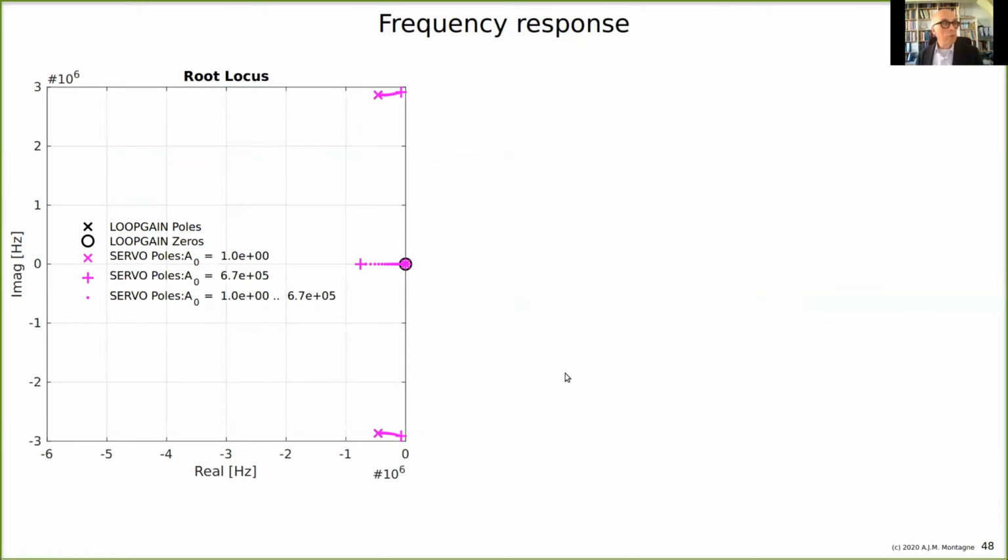And if we then make the root locus for our amplifier, then we see that the poles are moving closely, these complex poles, closely to the imaginary axis. So I'm expecting a lot of ringing and almost unstable behavior. So this is the dominant pole, and these are non-dominant poles. You see here, the frequency here is 3 megahertz, and this is less than a megahertz. So the bandwidth of the amplifier will be less than a megahertz. But at about 3 megahertz, I find non-dominant poles.